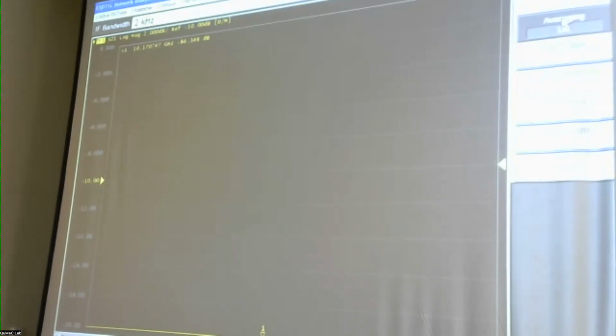By the way, this is just signal processing in general. This is true for anything. If you have a signal which is always going to come back in the same phase, because here, remember, what you are measuring is phase sensitive, extracted with reference to the original signal you are sending in. So every time it measures the same quantity, the signal part is going to have the same phase. So when you add it, it will add coherently.